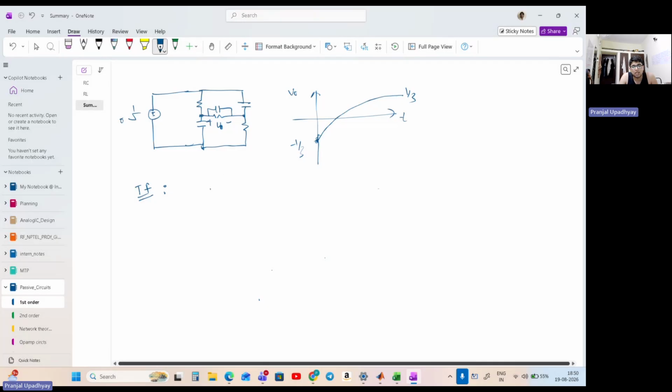So this basically just means that the difference of the low pass and the high pass system must be zero. So we can just easily establish that it can be expressed by 1 divided by (1 plus SRC) minus SRC divided by (1 plus SRC), right? And when this is equal to 0, that is when this V naught will be 0.